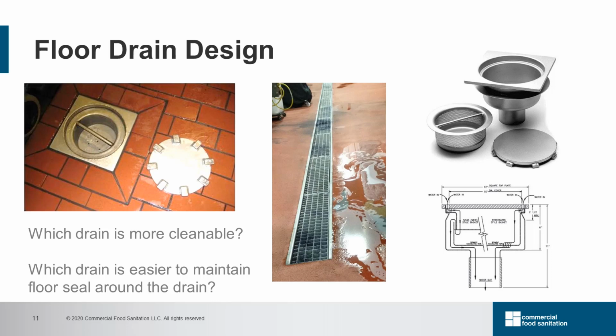The hygienic design requirements for drains include the use of corrosion-resistant materials, and the surface should be smooth and easy to clean. Baskets with filters are provided to prevent materials from blocking the sewer system. A good drain is designed with a water seal and a P-trap.